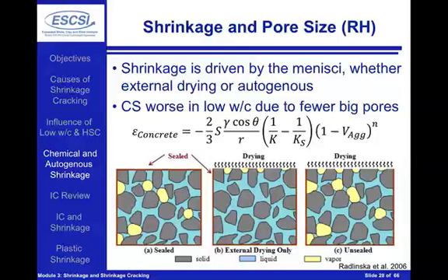The amount of shrinkage in our concrete is really going to be related through all of these factors that we see inside of the first equation, where we're going to start to see that the shrinkage of the concrete is equal to S, which is the saturation factor, gamma, which is the surface tension of the fluid, R, which is the pore size or the radius of the meniscus that's really emptying out, the size of the pores that are essentially emptying out of the system.